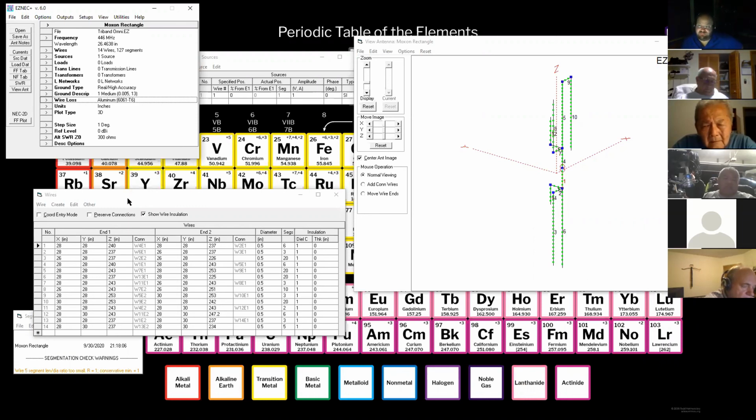Sometimes I get into the nitty gritty. I'm trying to squeak out that last 1/10 of a dB, because if I can find 1/10 of a dB in 10 places, hey, I got 1 dB back. But does that 1 dB really matter in the grand scheme of things? No, absolutely not. For me, it's just the game. I'm trying to get absolutely as much as I can out of it. That's why my tuner is at the feed point, and that's why I'm running high dollar 1/2-inch foam core coax even on my HF stuff. The loss doesn't matter there, but it's about taking it to the absolute extreme.